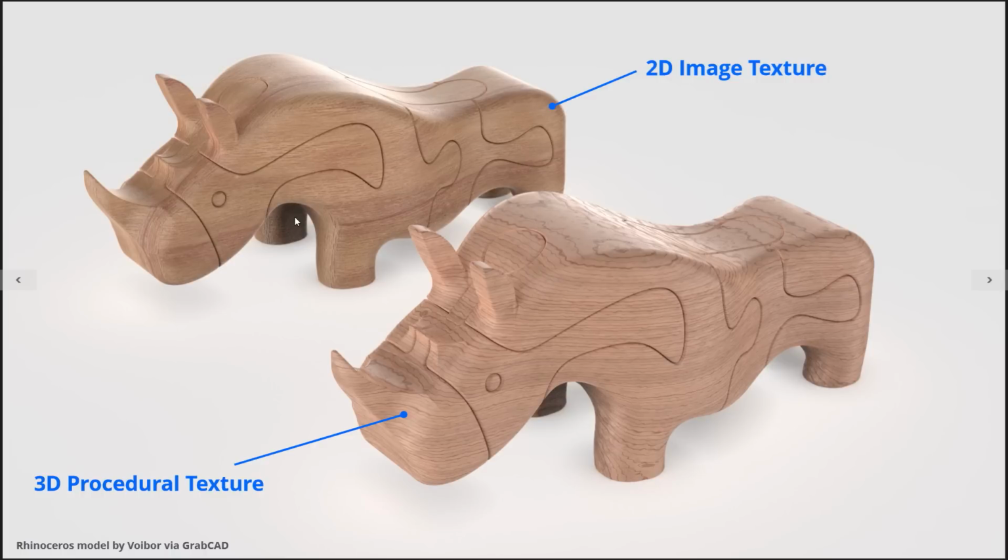And if you've ever tried putting a 2D texture onto a highly organic form, then this is probably going to be something that's familiar to you. So again, with 2D textures, your limitations are how it applies onto that piece of geometry. Whereas a 3D or procedural texture, in this case it's actually a 3D procedural, is completely seamless. If you take a look at the surfaces, that wood is actually mapping completely around the surfaces in a totally seamless way. So that's just a quick primer. Basically, think raster graphics versus vector graphics for your textures.